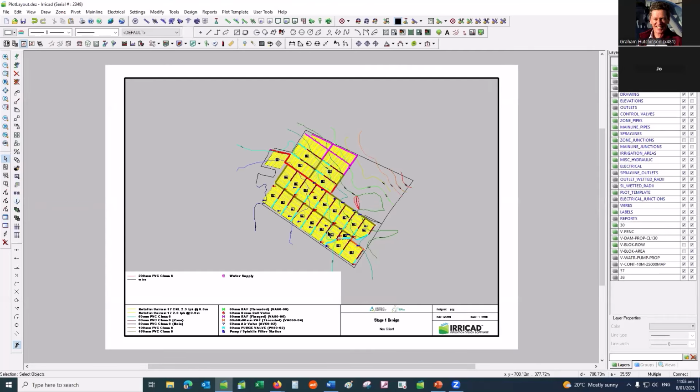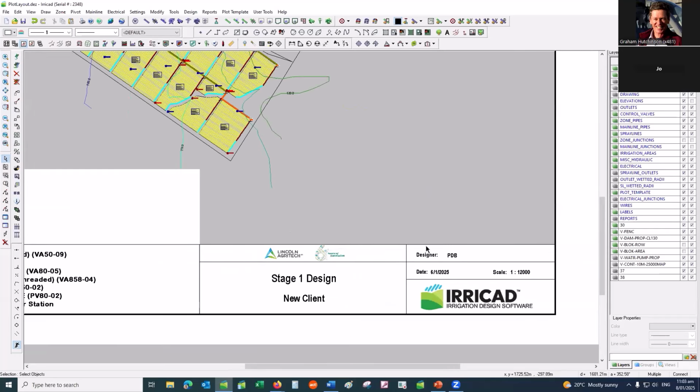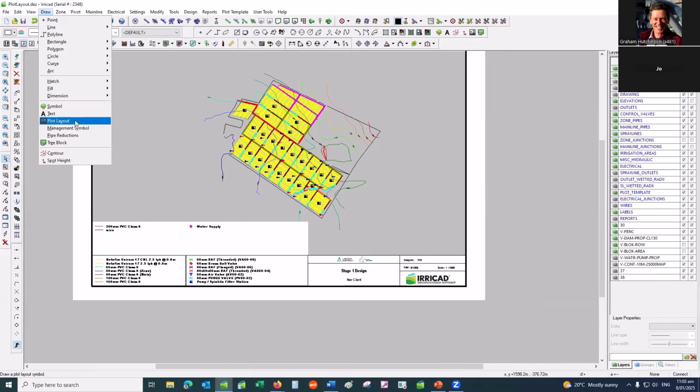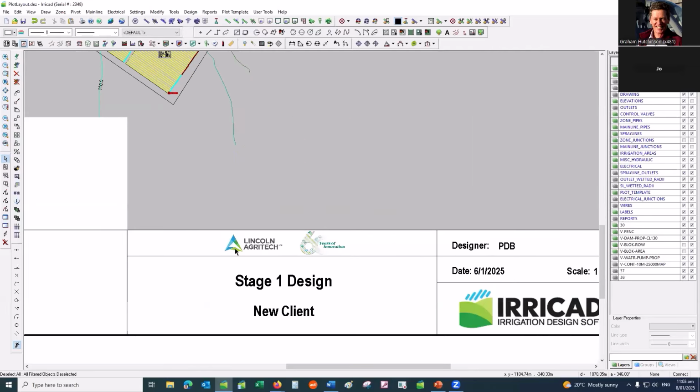Your logo was a low profile rectangular logo. If someone had a higher profile rectangular logo, can it be put in the space for the design and then movable once the legend has been created? You would need to explode the legend to be able to get this out. So when you are placing it through the draw plot layout, it is one complete symbol. You can make temporary changes simply by exploding and making the changes you want. Just remember that all of these lines, etc., are editable.